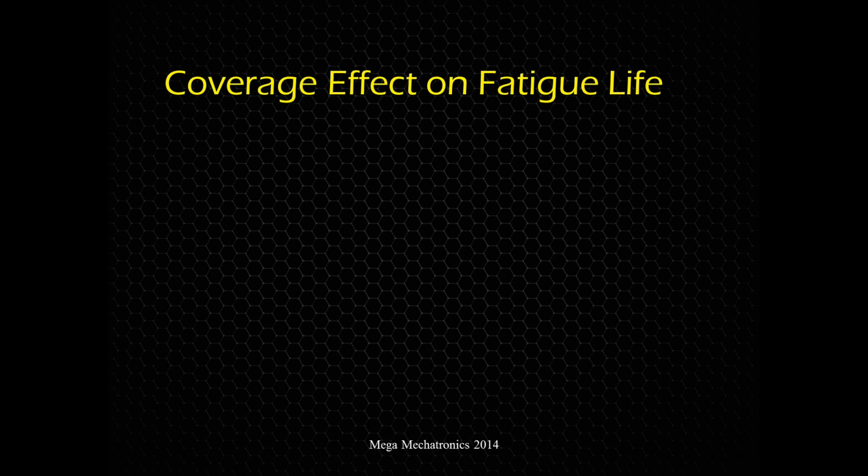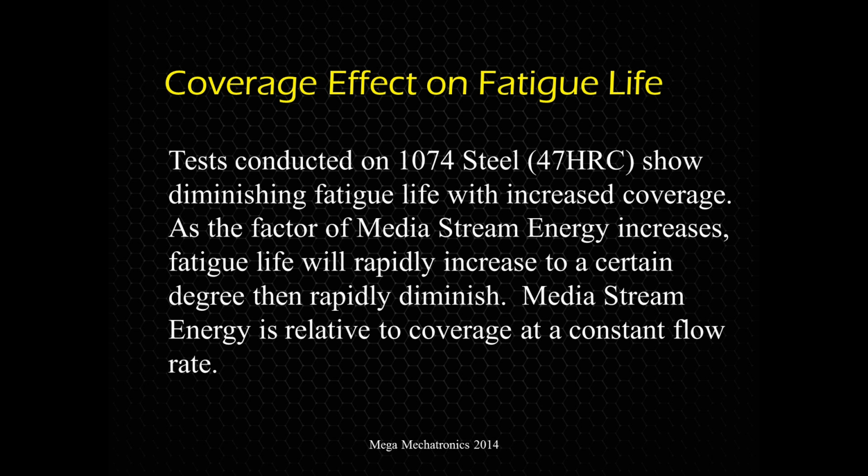Now we're going to get into the optimization of the process, and we're going to be looking at the fatigue life and the amount of residual stress that you are imparting into the surface. Here's a test we have, and this really does depend on the material, so we're only going to look at a few examples. With your application, you're going to have to find ways to optimize that, but what we're looking at are the concepts behind this optimization process, and how you diminish the fatigue life with increasing the coverage.